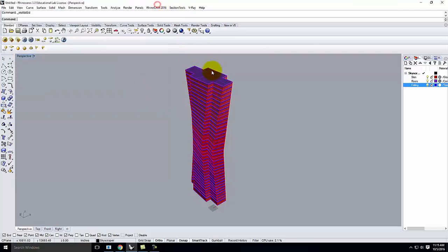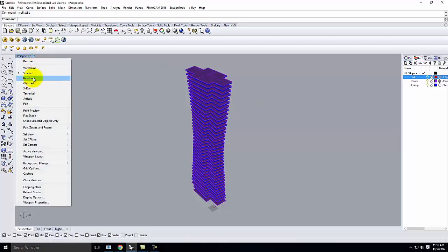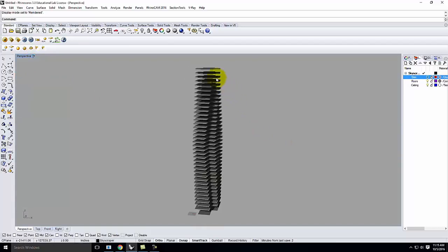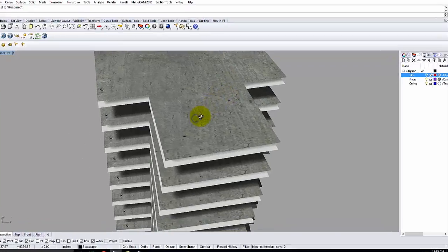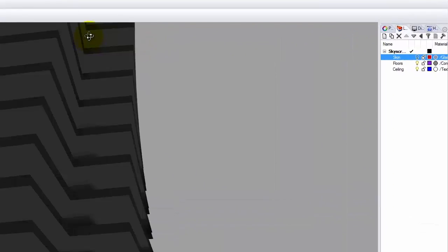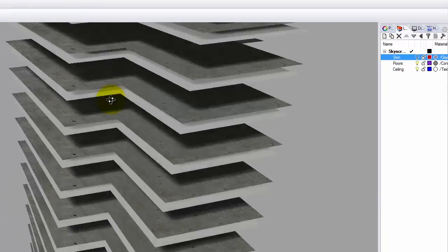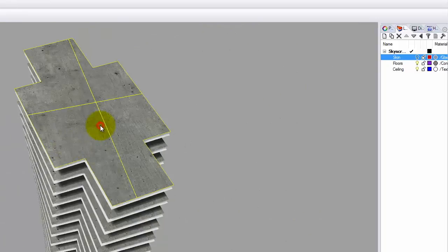We should be able to see those if I turn off the skin here and go into my rendered view, right? We should be able to see the concrete for the floors. We should get the white for the ceilings, which is good. The texture mapping on these is not exactly of a density that is appropriate just yet. So let's go ahead and modify that.